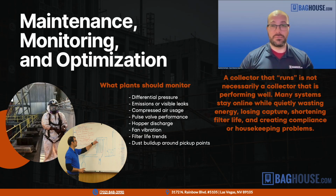Then you're going to obviously want to monitor for any leaks or emissions, whether it's coming out of the dust collector, coming out of the exhaust stack, but also in the plant where you might see fugitive dust coming out of some of the sources. If it's not collecting enough of the dust and the dust is getting out, it means there's a problem somewhere.